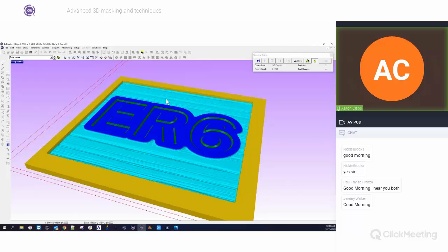This is what the idea of masking can allow you to do. You don't have to stack all of these effects on top of each other using 3D. If you really wanted to, you could go into EnRoute and create this same sign all in 3D. But this is going to cut much faster, and it's going to be easier to modify down the road. You can also change toolpaths if you need to, or change out interchangeable pieces. It's almost like a template.